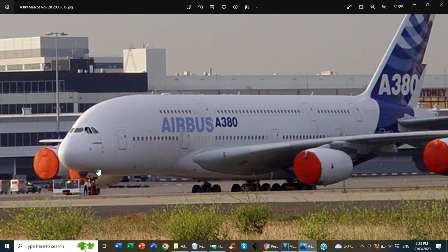You can see that the combination is well below the level of the taxiway. And that tractor has to haul that 545 tonne up that grade onto that taxiway. Small grades matter. You have to have the tractive effort to do the job that is required.